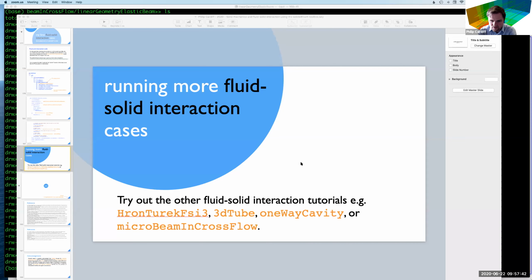Which decomposition scheme did you find achieves the best speedup for FSI? Lufang, hi. I'm not sure. Typically, I just use Scotch or Metis, and I don't check that much. I know you're going to be limited by the size of the interface, because the full interface gets assembled on every core in parallel. So that is a bit of an inefficiency, but of the schemes, I guess Metis or Scotch works probably best.